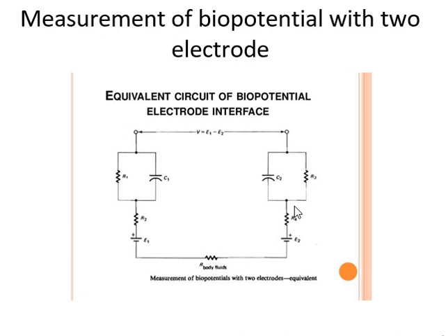The three basic types of biopotential electrodes used to measure biomedical measurements are microelectrodes, skin surface electrodes, and needle electrodes. A very popular electrode is silver chloride, because it has a very low half-cell potential, approximately 220 mV, and is easy to manufacture. These electrodes are non-polarized electrodes. They allow current to pass across the interface between the electrolyte and